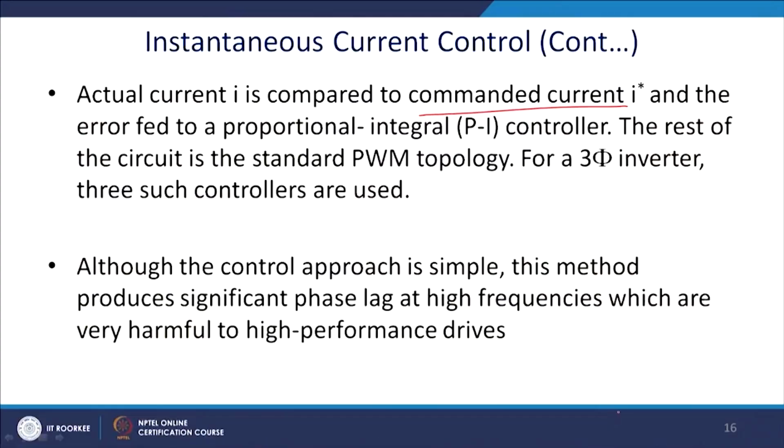Although the control approach is simple, this method produces significant phase lag, which I pointed out. There is a delay in estimation, and of course the delay can be compensated by the control circuits with a lead compensator, but designing a lead compensator will also be difficult because this delay is not constant.